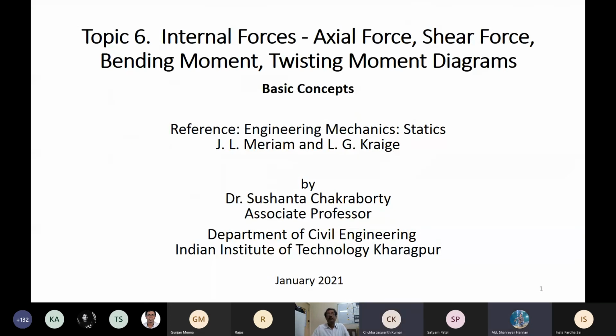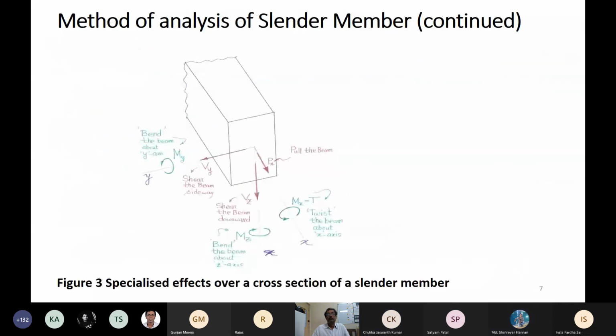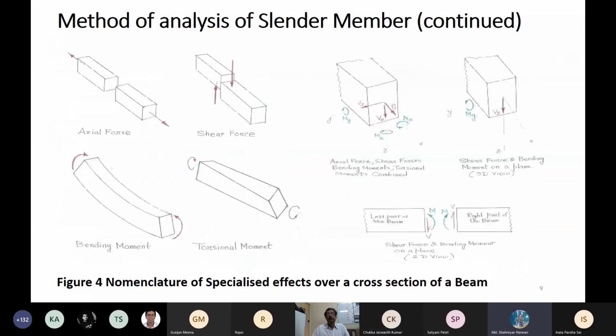So in the 2D part, why are you not taking Vx and Vy? In the 2D part? So yes, sir, this slide. This is depending upon the application. Suppose in your building where you are sitting now on your chair, so that beam is primarily supporting a vertical load. If it is a vertical load, then the shear will be vertically down, and the moment will be mainly in this plane ZX.